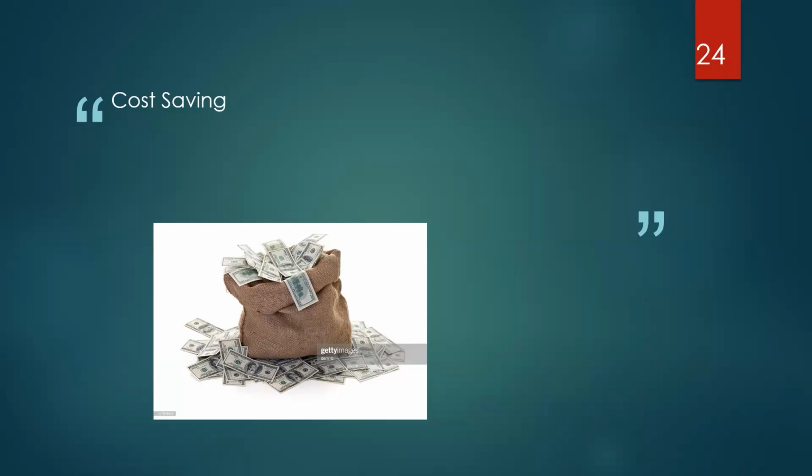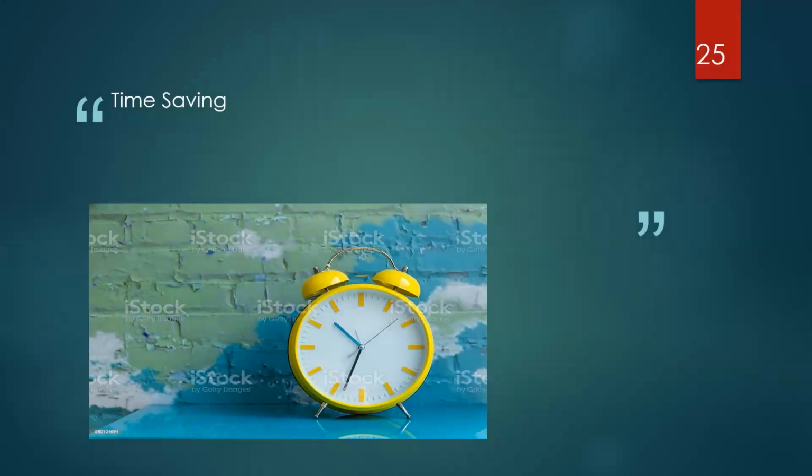It's a repeat. Okay, so cost saving. For all the reasons that I mentioned, how fast and efficient the CPT is, and how quickly you can get the data without converting anything, it has a tremendous cost saving. Not only that, you don't have to worry about lab testing. That's a cost saving. You don't have to transport the sample to a lab, maybe sometimes miles away. That's a cost saving. Also, the number of crew is typically less for a CPT than it is for other investigations, and also the footprint. So there's a lot of cost savings there. Time saving is obviously a lot faster than a boring. So there's tremendous time saving from using CPT for this kind of site and geology.